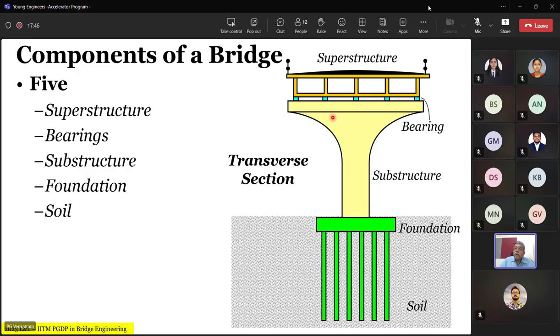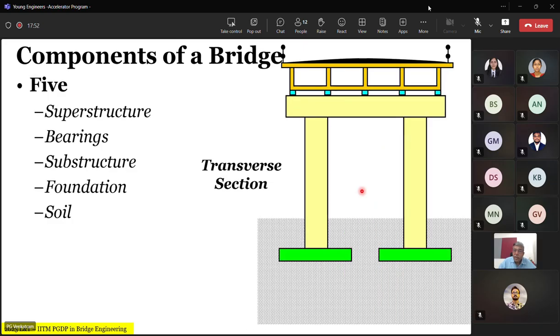So the most important junction is essentially where a superstructure joins the substructure. In the transverse direction, we can introduce a junction even within the substructure if you have a portal structure like this, and therefore we can have junctions in a variety of situations. So we should understand what controls our decision making, what the different types are, etc.